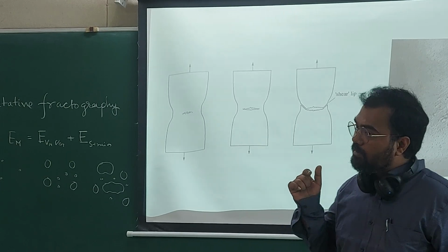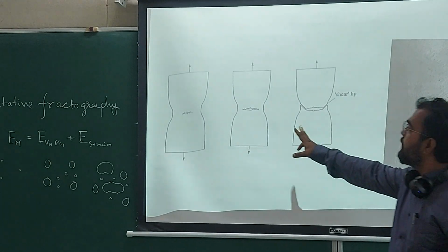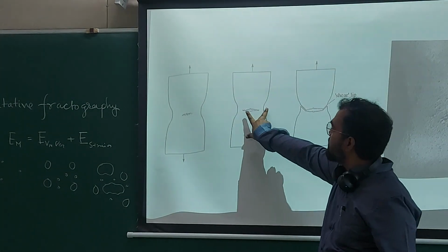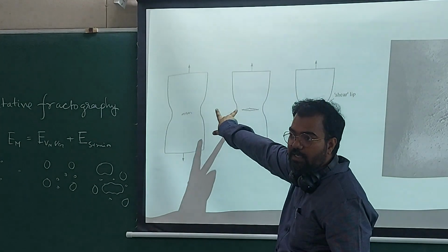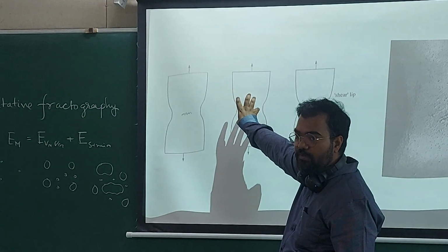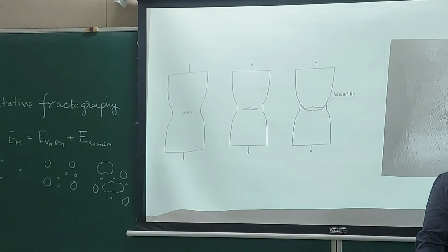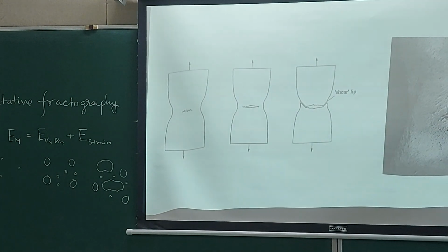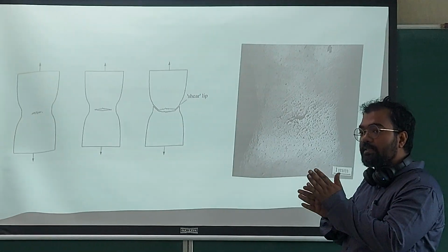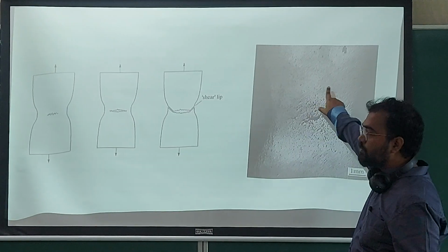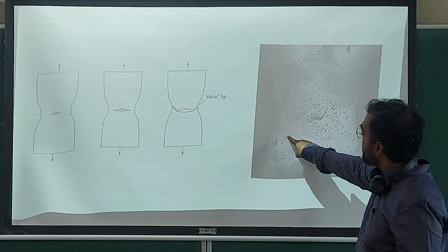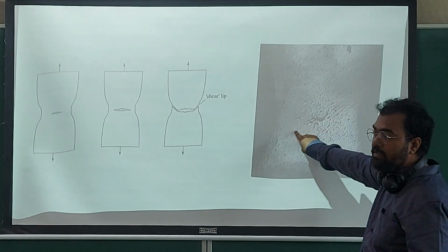So necking could have happened anywhere, but if the necking started here, the stress has increased here and it will keep on increasing there. Once initiated, the system will support the formation of that. Once a coalescence cluster becomes critical, the crack takes the lead there and all the other things will stop. And this will start propagating, and in its direction it will cut through all the voids.